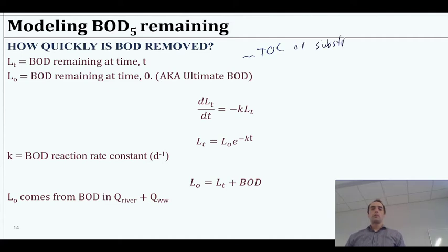Now, mostly we've talked about BOD in a 5-day measurement. 5-day measurement is pretty standard. That's important. But one thing that, if we're not careful, will get confusing is we can think that that's the total BOD in the solution. That's not actually true, because we could also do a BOD for 10 days. That would be a larger number than a BOD for 5 days. We gave it more time, there's more oxygen demanded, right? Because in 5 days, the bacteria don't eat everything, they just eat a fair amount. And 5 days is just practical, so we do 5 days.